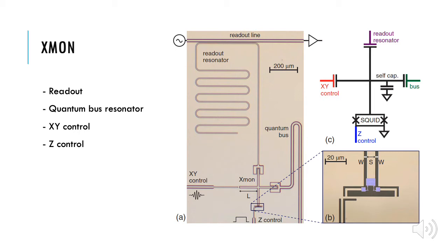The cross is the qubit capacitor, connected at the bottom to the tunable Josephson junction, which is formed by the rectangular ring-shaped superconducting quantum interference device, which is also known as SQUID. 3 of the connections are easily accomplished with a capacitor, by coupling each of the qubit's arm to a distinct element, as the qubit is connected to ground. An advantage of this approach is that each coupling can be tuned and achieve a specific function individually.